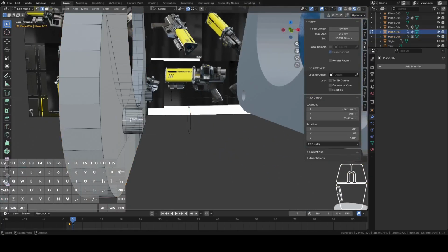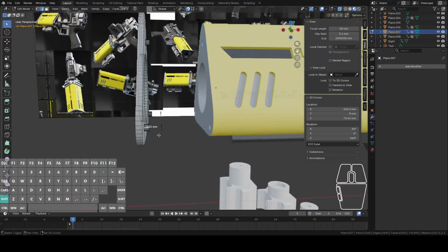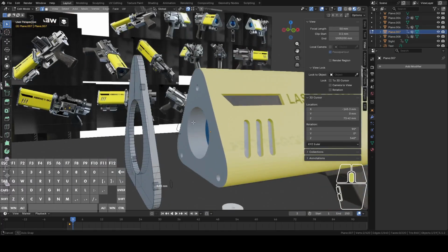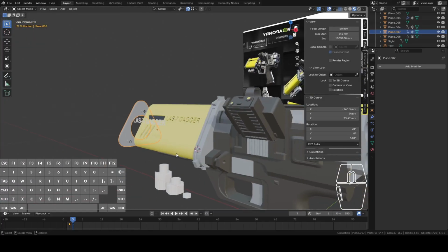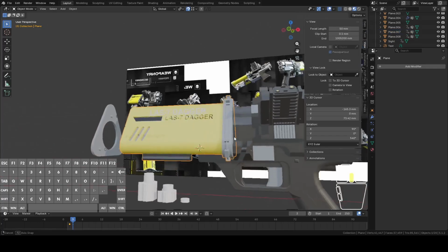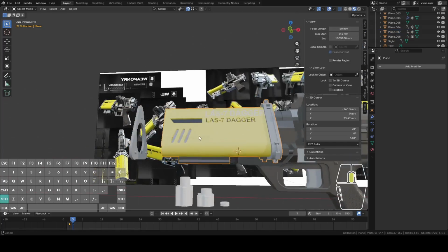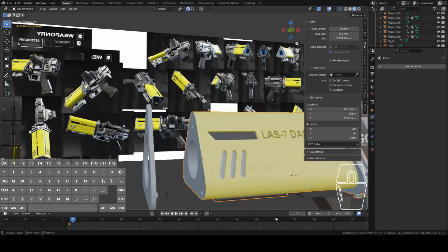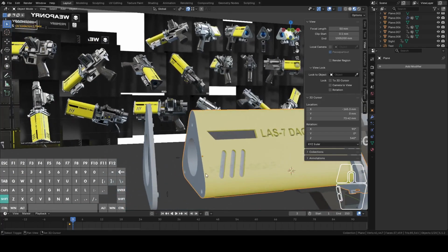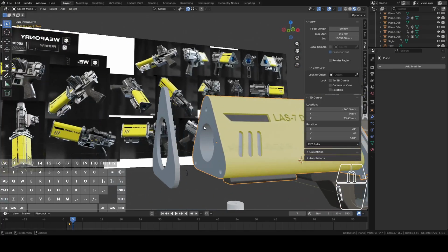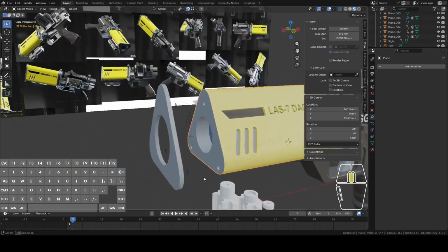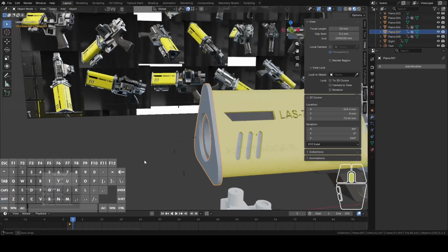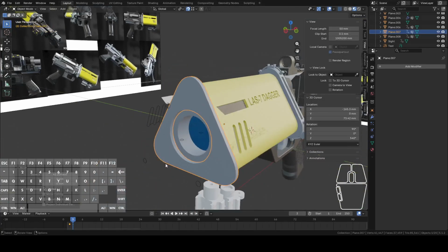This faceplate here fits flush. This is actually 5, so that should be plenty. Doesn't really matter. A little less for printing. And those should just glue right on there, and we'll print it with this face on the print bed, so it's gonna print standing up. That way, this part no longer attached, it doesn't have to print a whole bunch of support going all the way around. Should be fine, and we'll just glue that in place. Like so.